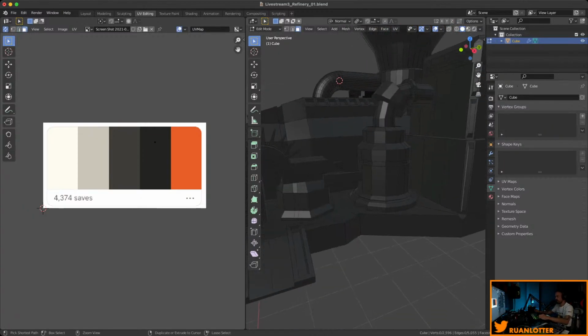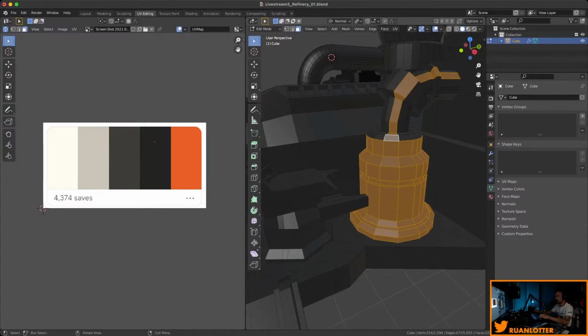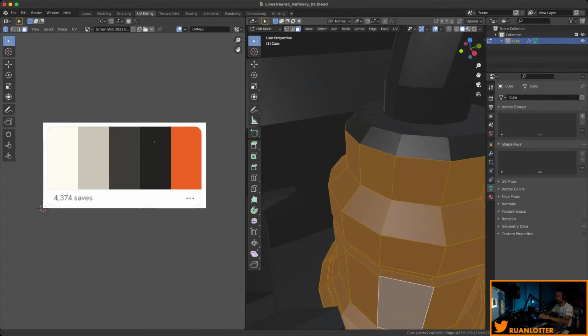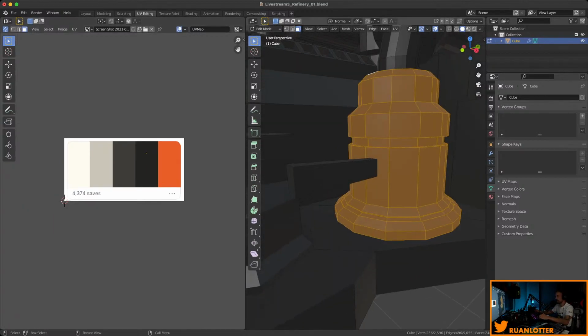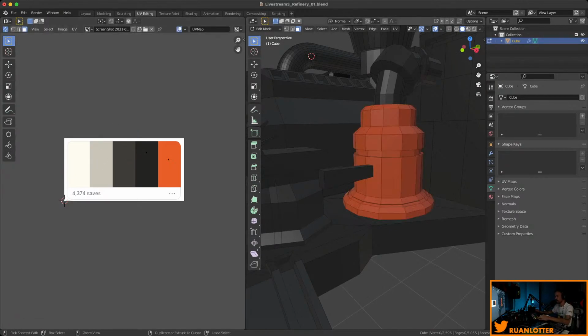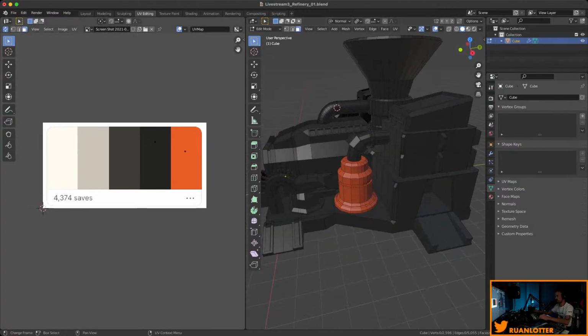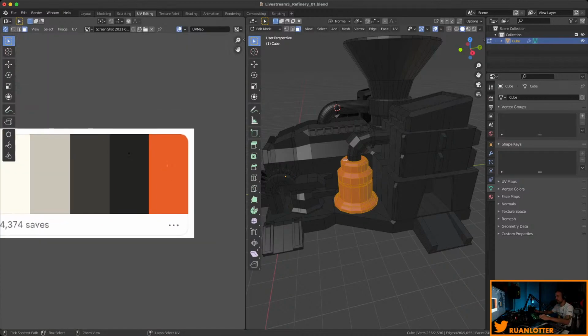So now you can select some of these objects. I'm going to do that, and then grow that selection by pressing Control plus, and then maybe select those ones around, and maybe those ones. So now with those faces selected, I'll press G on this side, grab it and maybe move it to the orange, and then that whole section will be that color, because all those faces are basically compressed into that one dot, because I did a scale 0.